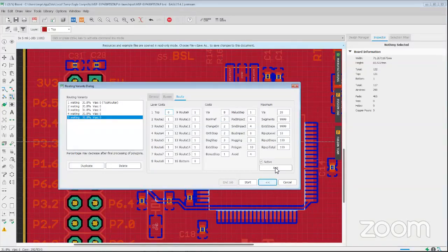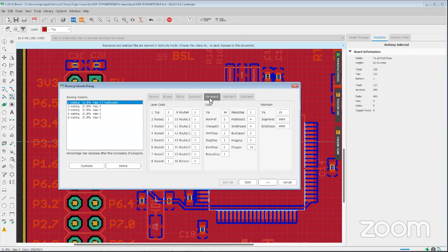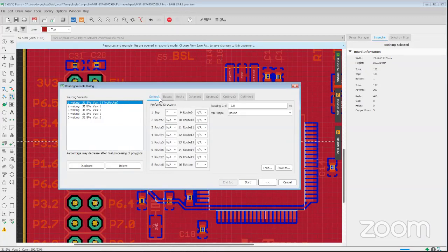And we can add multiple runs of these. You'll notice in the top router there are runs to clean. So if we go to top router, you'll see we have the same buses, we have route. You see how expensive route makes vias. You can see here. And then you have these optimized runs. And the idea of the optimized runs is to go multiple times trying to clean up and minimize the number of vias. And they're all set up this way.